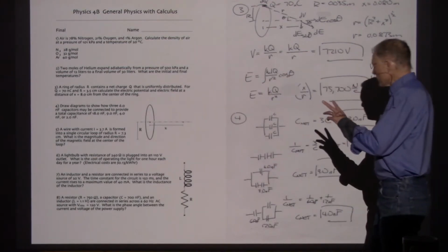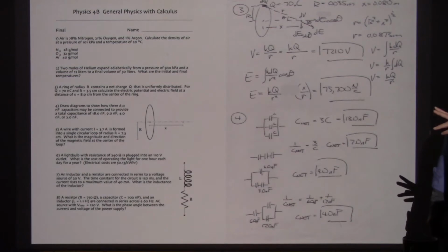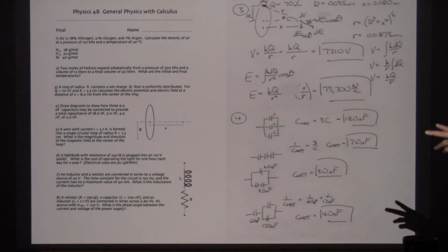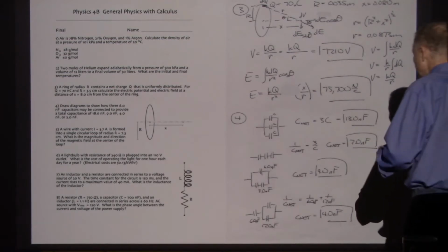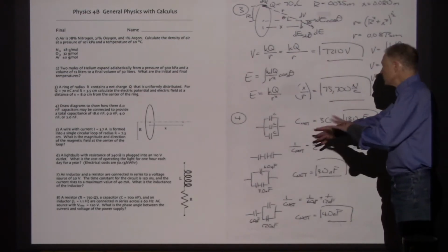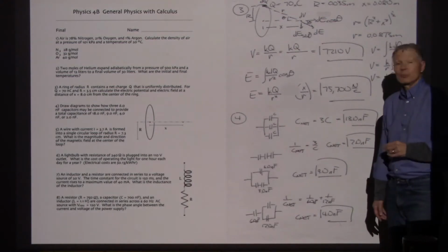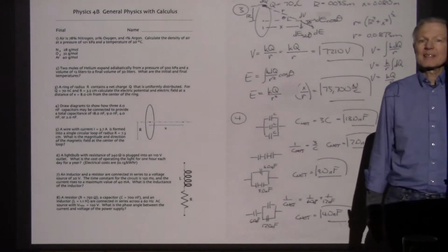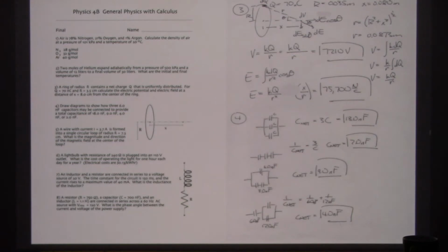Now, those 2 capacitors in series, if I use the formulas, are going to have a net capacitance of 3. I'm going to end up dividing the 6 by 2 and getting a 3, and then 6 and 3 combined would be 9 nanofarads. Now I could move the individual capacitors around, but they're all the same. So since they all have the same capacitance, those are not going to give us any different numbers.